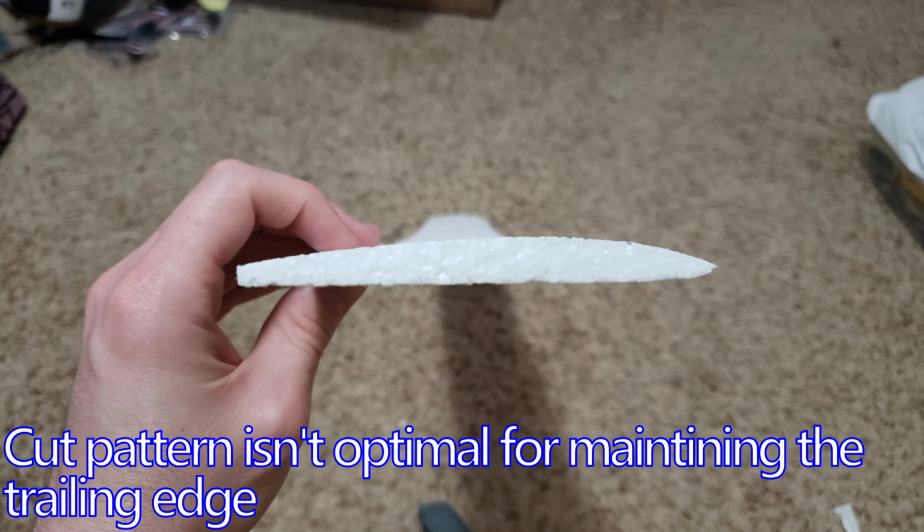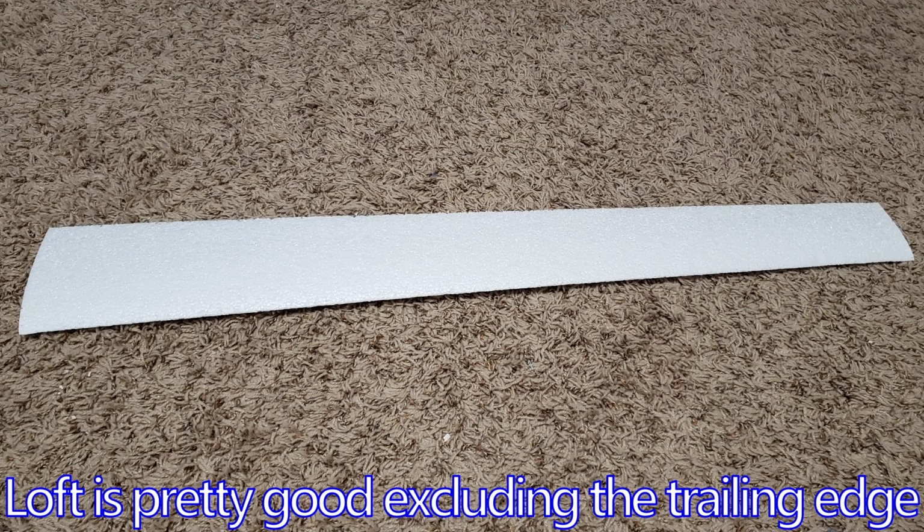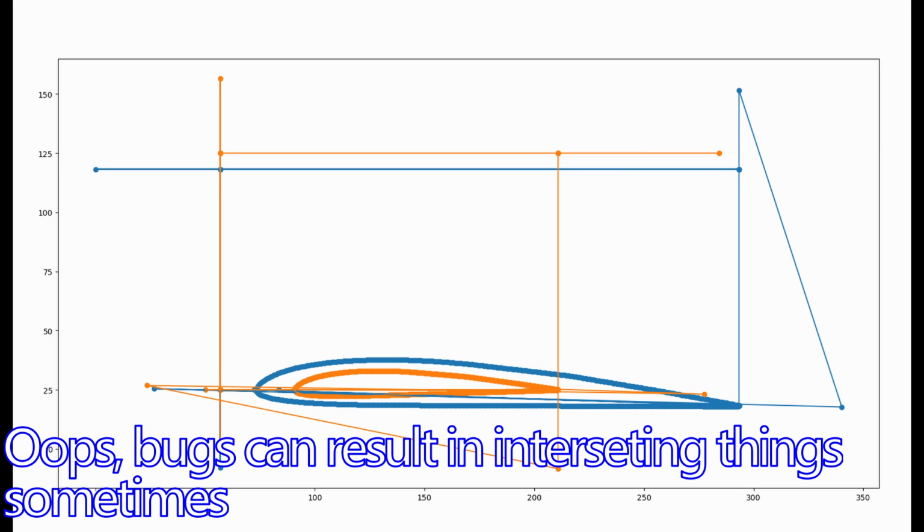So overall, the cut wasn't too bad on the forward section of the wing, but when it got to the trailing edge, the way it looped around and the way it was cutting wasn't very good for actually maintaining the trailing edge. So at this point, I realized that I needed to probably re-architect a lot of the code that dealt with going from cross sections to actual toolpaths. So I ended up implementing a step in between, which I just called cut path in the software. And so you end up forming a cut path, and then the cut path goes directly into a tool path.